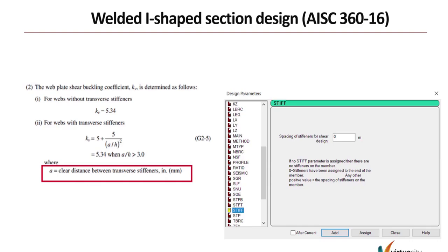The reason is that most of these tapered web sections used in this kind of structure have a significant depth, just like a plate girder. When they experience immense stresses, they might have a tendency to buckle out of plane. So, to resist buckling out of plane, we need to provide some stiffeners vertically.